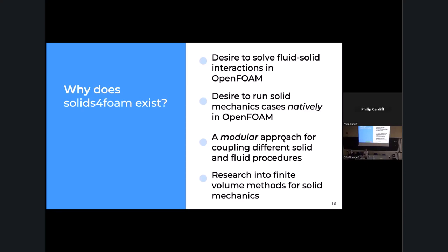So originally, when you wanted to do FSI in the OpenFOAM-style approach, if you wanted one type of fluid solver like pimpleFoam and another type of solid solver, you had to just copy and paste them into the same solver. So if you wanted to change something, you had to make a new solver. Having a modular fluid and a modular solid means that at runtime, you can select which ones you want to use. So I'll talk a little bit about that.